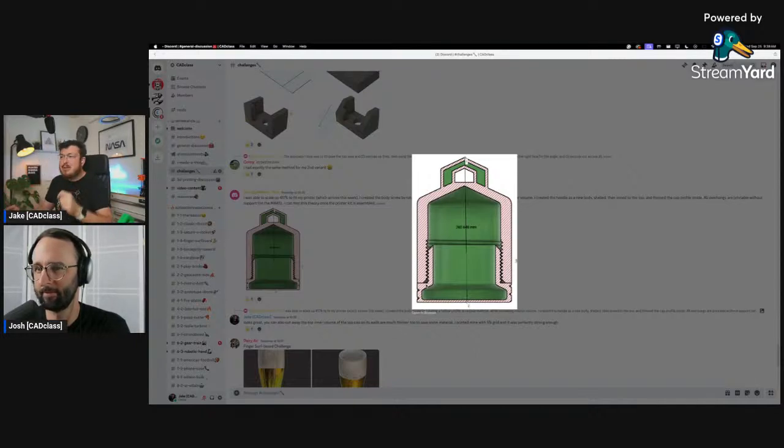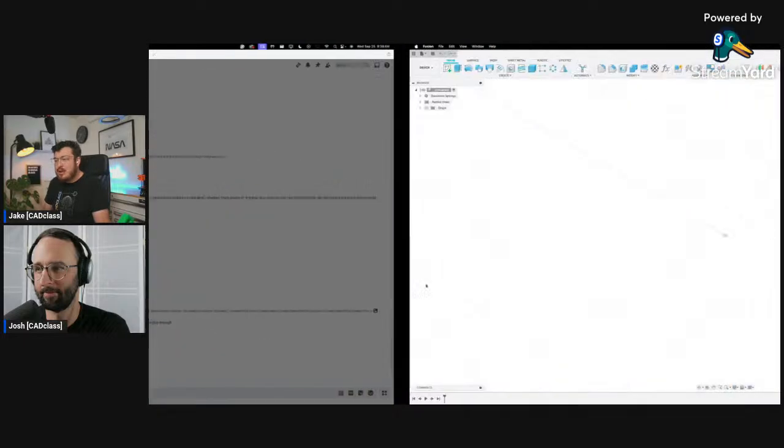One thing that I found really strange is that when you have a normal part that is, let's say, 4 walls thick, 1.6 millimeters, that's nice and strong on small scale. And then as soon as you blow it up to be 500 times, you've now got wall, infill, wall. And it's actually less strong. So you're better off blowing it up and then gutting more material, and that will give you a stronger print, which is very, very strange, but that's totally how it works.